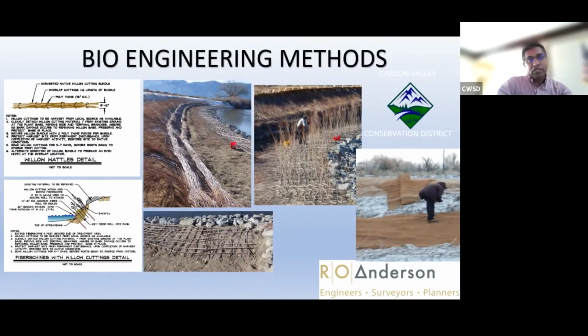And these are bioengineering methods. They said we haven't really used much, but just to please everyone, we try to do some of these willow plantings. And once the contractor is done, then Rich will have his team go out there and do these coir fabric mats, live plants, basically seeding the top of the banks. Obviously, when you have the construction vehicles going around, you make all kinds of mess. So we try to restore it so that the landowners are happy. Put a lot of seeding, willows.